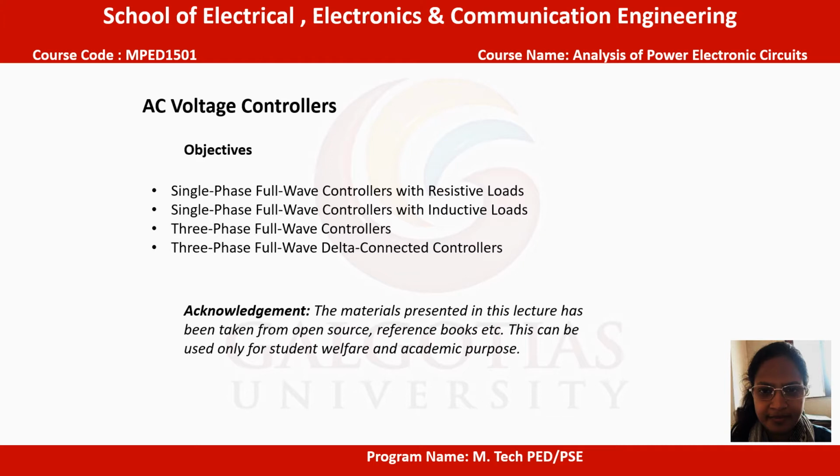For applications up to 400 Hz, if triacs are available to meet the voltage and current ratings of a particular application, triacs are most commonly used. Further, due to line or natural commutation, there is no need of extra commutation circuitry, and the circuits for AC voltage controllers are very simple.